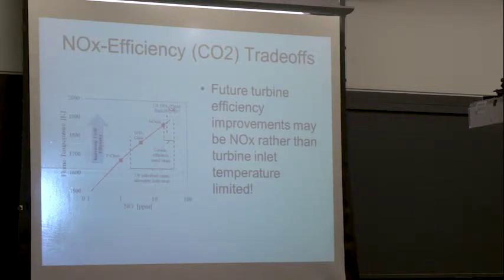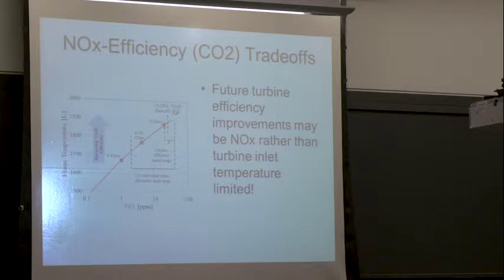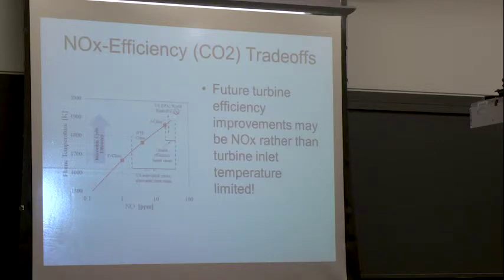You'd say, well, given the world that I live in, I'm going to be at 20 millisecond residence time, I'm going to make about 50 or 60 parts per million of NO. Well, one thing you could do is you could reduce residence time, right? You can make the combustor shorter. And that is a strategy. What's the downside?